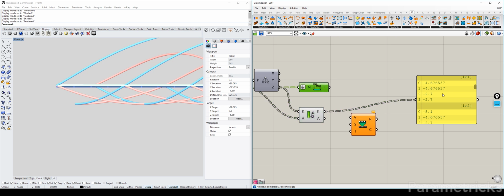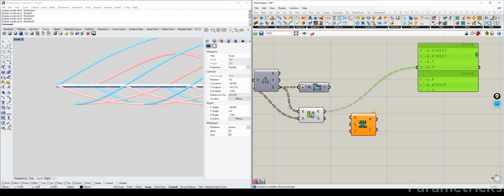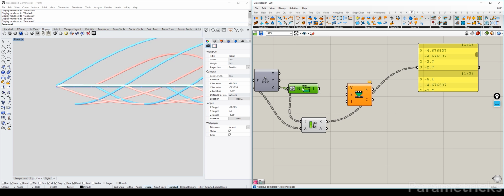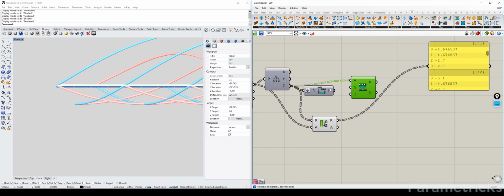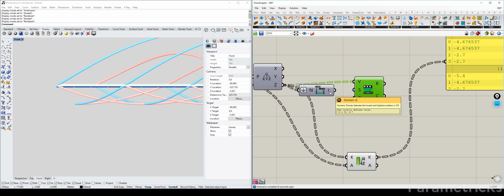Basically, what I want to do is turn these negative values, or whatever values we give it, into a more unitized list. And you'll see what I mean if I use the remap component. I'm going to remap all these values prior to sorting, because it doesn't really matter, and put it into this. This is the source.